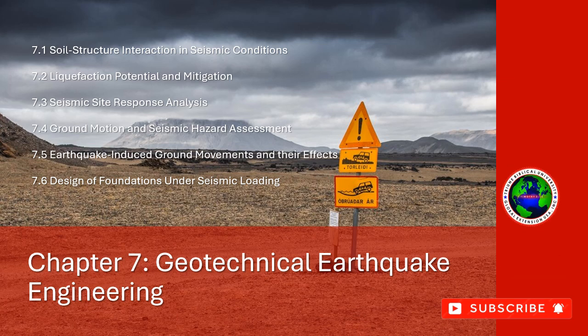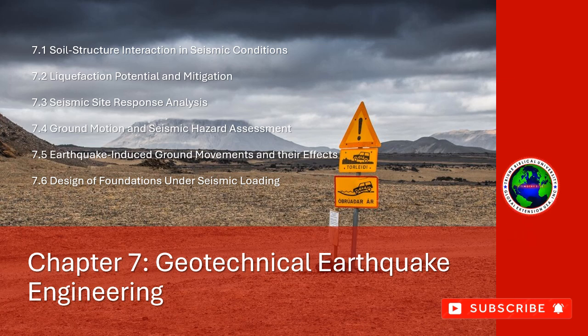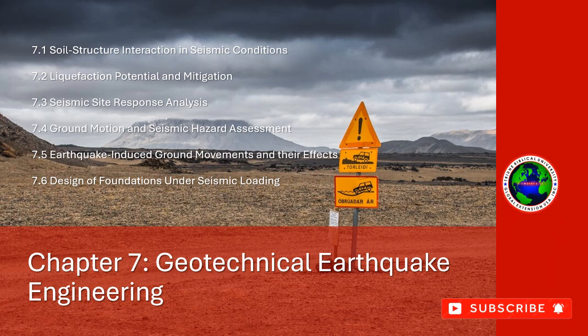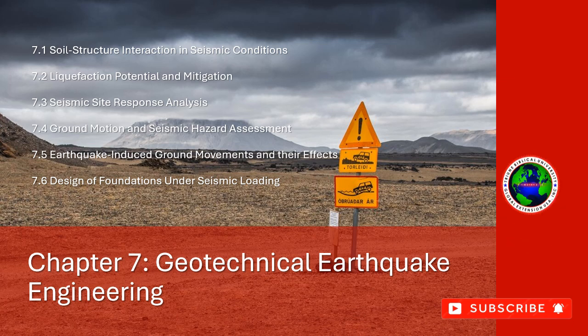Liquefaction occurs when saturated soils lose their strength and behave like a liquid during seismic shaking. In areas prone to liquefaction, foundations must be designed to withstand the potential loss of soil strength and settlement. Mitigation measures: use of deep foundations that penetrate below the liquefiable layers to reach more stable soils.